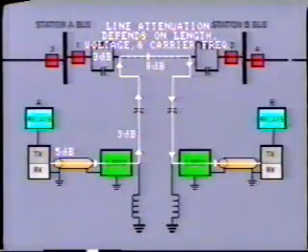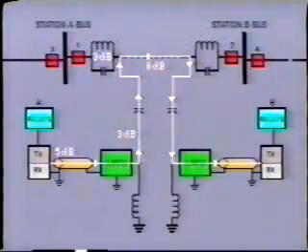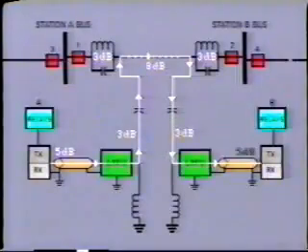Higher line voltage leads to lower attenuation, while higher carrier frequency increases the loss. At the receiving end of the line, the signal will be further attenuated by the line tuner, 3 dB, the coupling equipment, 3 dB, and the receiving equipment, 5 dB.